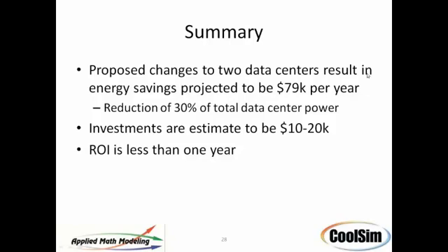I tend to work in flow rates and delta T's and let the pressure settle itself out. The floor pressure is not that high in these data centers. The fans don't produce a whole lot of pressure. They can't, they're just not designed to do it. So I don't know what a rule of thumb would be. It's really hard to say an absolute value of pressure. By the way, it varies across the floor, so it's not even uniform.